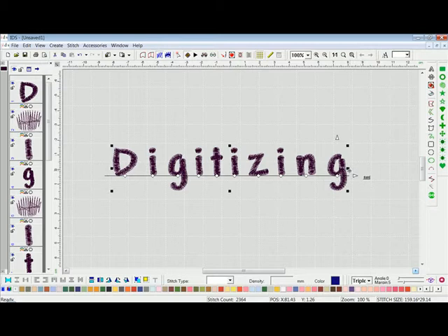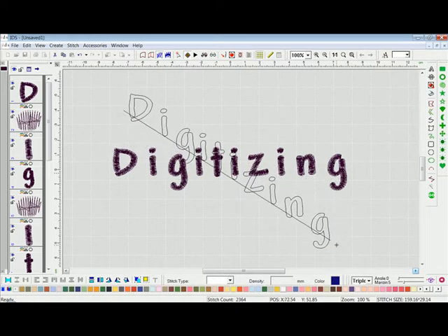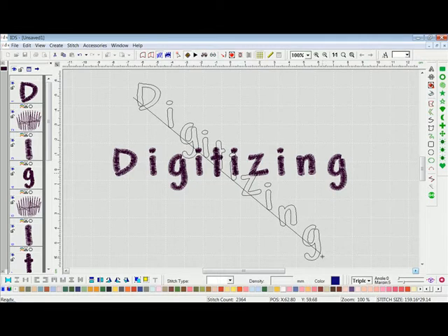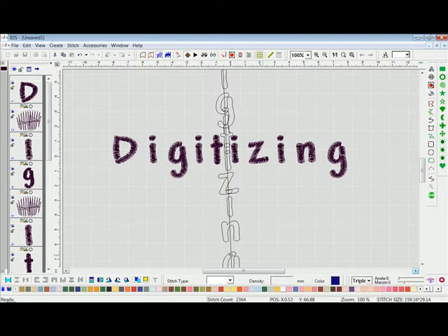Another arrow that's directly to the right of the last letter is an arrow pointing up. As I place my cursor over that arrow, again it will turn into a crosshair. Once I get the crosshair, I will left click, hold, and drag, and I'm dragging down to the bottom right, and I'm dragging more in a circle, and as I drag in a circle, I can stair step my letters. I can bring them completely vertical. So you can make your letters vertical without choosing that vertical option in your insert text box.